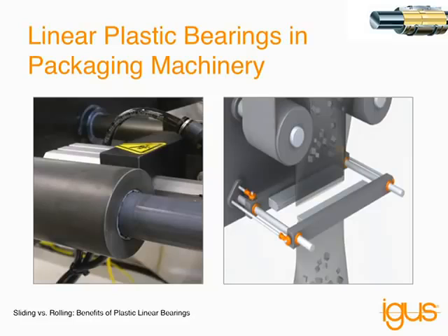One absolutely core industry for plastic composite bearings is packaging, the packaging machinery business. A lot of applications, one of the classic ones would be the welding jaws on vertical form fill seal machines. These are basically machines that have a hopper above that might dispense chips into a bag, and these welding bars or welding jaws are the parts that close, usually through heat.